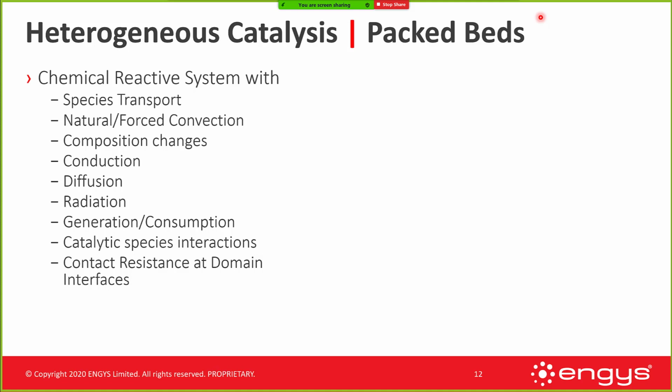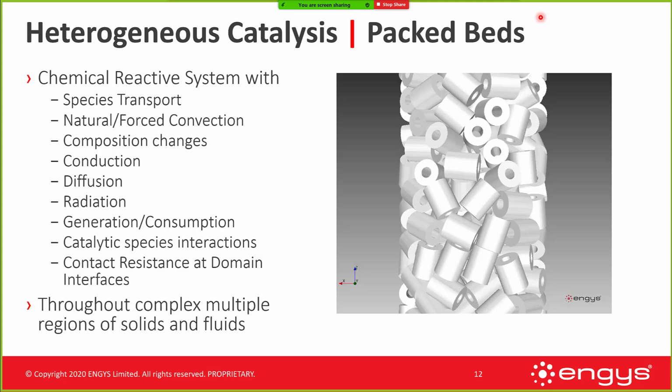Packed beds can be chemically reactive systems with species transport, natural and forced convection. There's composition changes because of the species transport. There's conduction. There's diffusion. There can be radiation if it's really hot. There's generation and consumption of mass and energy. There can also be interaction with catalytic species inside of the solid. And as I mentioned before, there can be contact resistance at domain interfaces. Now, with all of those modeling challenges, this is actually a simulation through complex multiple regions of solids and fluids.